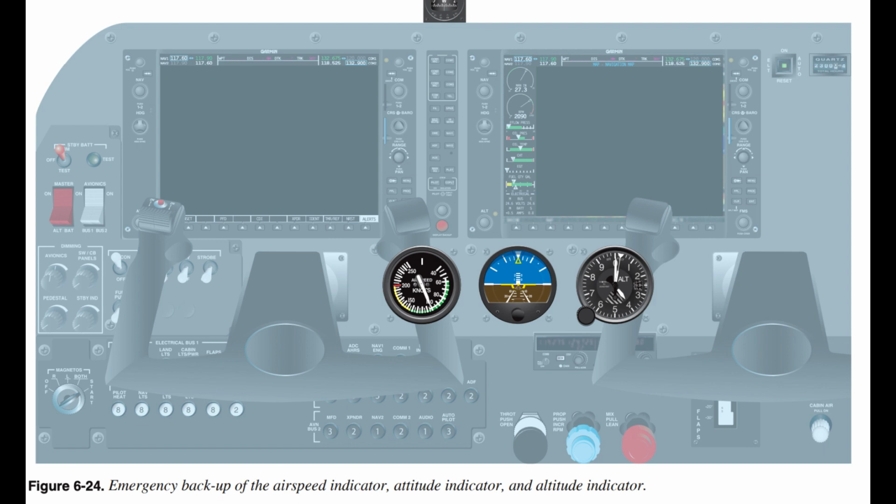Pilots flying under visual flight rules, VFR, maneuver their aircraft by reference to the natural horizon, utilizing specific reference points on the aircraft. In order to operate the aircraft in other than VFR weather, with no visual reference to the natural horizon, pilots need to develop additional skills. These skills come from the ability to maneuver the aircraft by reference to flight instruments alone. These flight instruments replicate all the same key elements that a VFR pilot utilizes during a normal flight. The natural horizon is replicated on the attitude indicator by the artificial horizon.